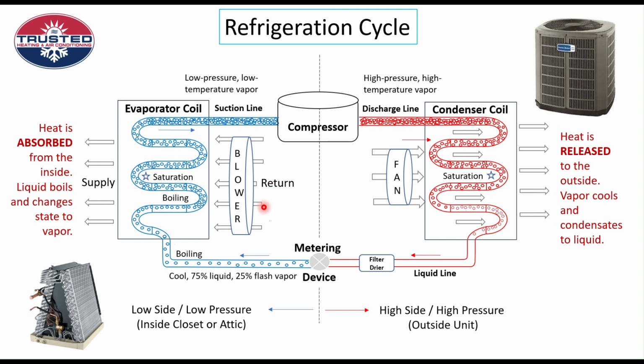So it's important when we think about things that a homeowner could do, your filter is very important. That's the number one thing a homeowner can do, is ensure that your filter is clean, because you want sufficient airflow to come across this coil so that it can effectively and efficiently cool your house.